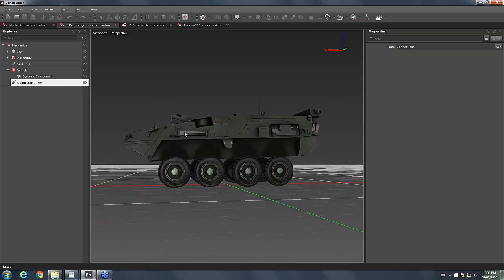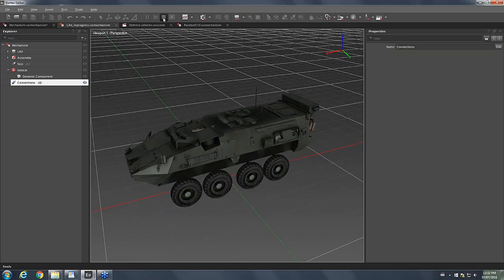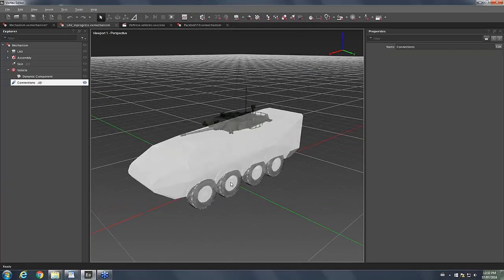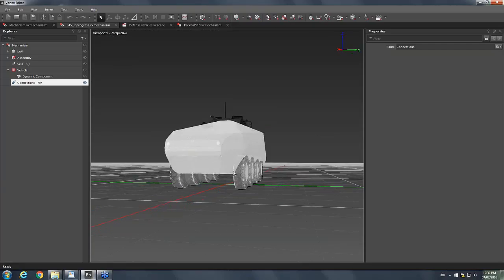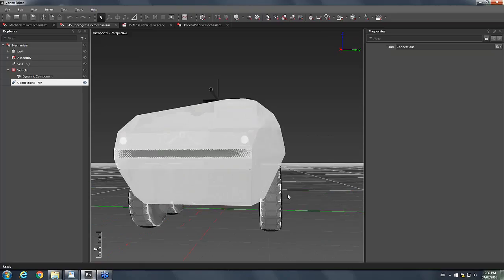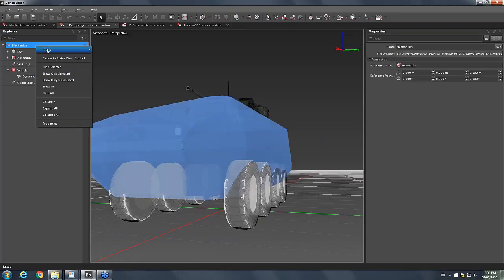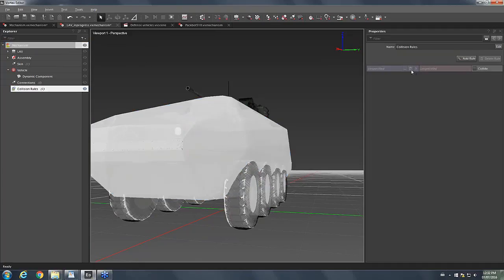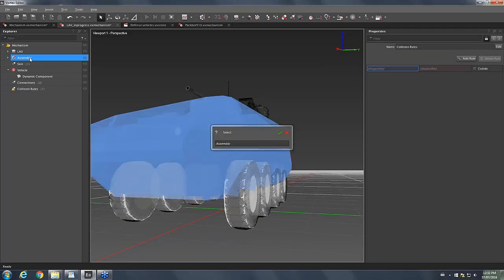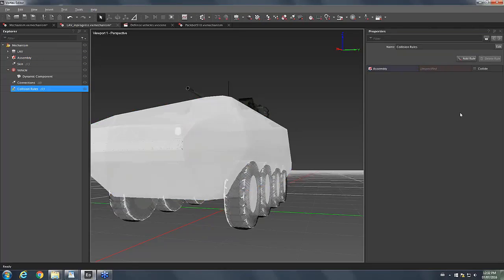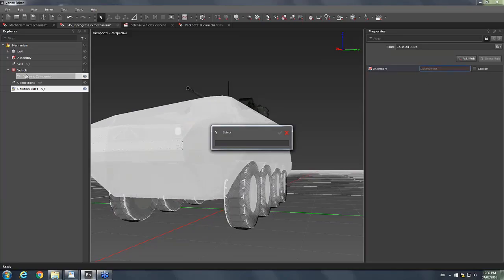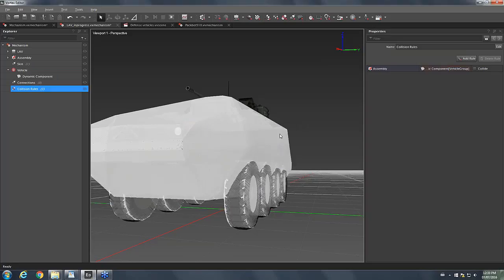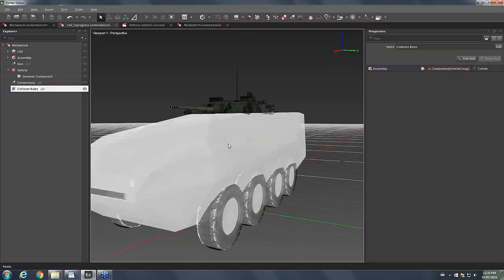Not quite what we want. There's something weird going on. So we're going to stop and we're going to look again. The collision geometry of the hull is intersecting the collision geometry generated by the vehicle system. So first, we need to tell the computer, okay, there's a collision rule that you need to obey where the assembly that contains the hull will not collide, so I leave this checkbox empty, with the dynamic component of the vehicle system. So in this case, we've got the vehicle group, so I check it, and I save it.